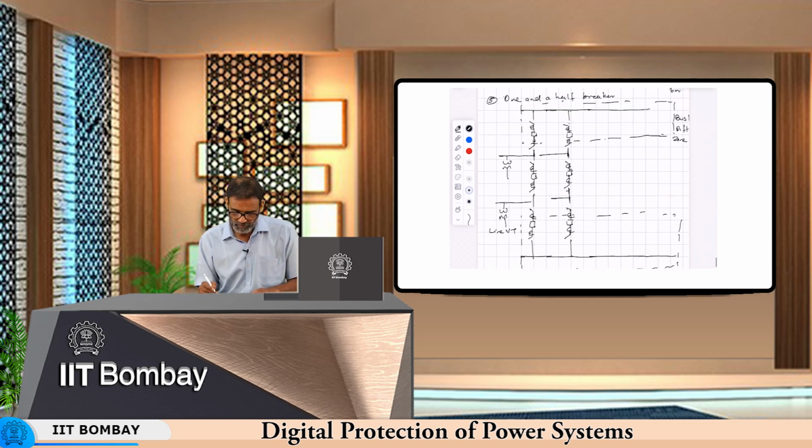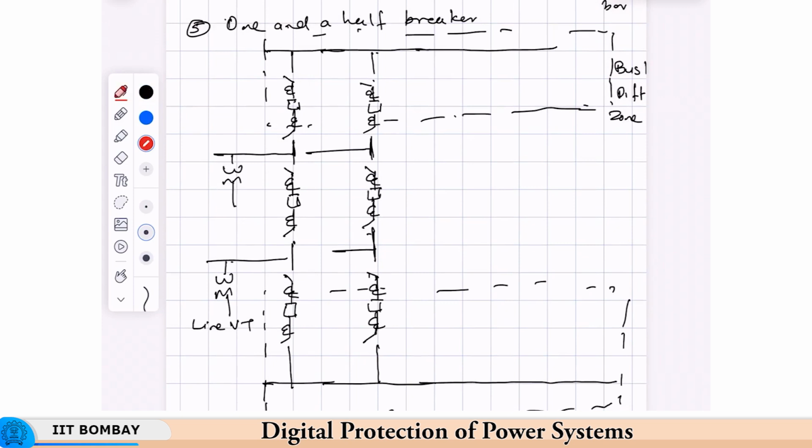And the line protection similarly will have to summate the currents from two CTs. So, this will be, say, L1 if it is line 1, and then L2, summating these two CTs. Okay.